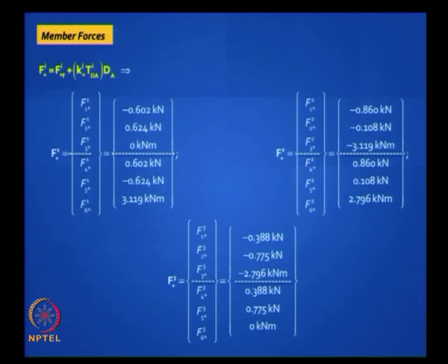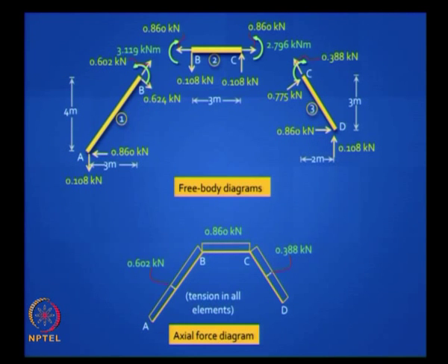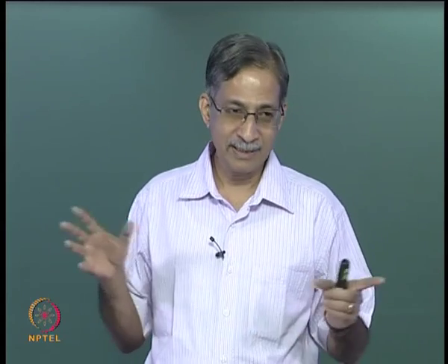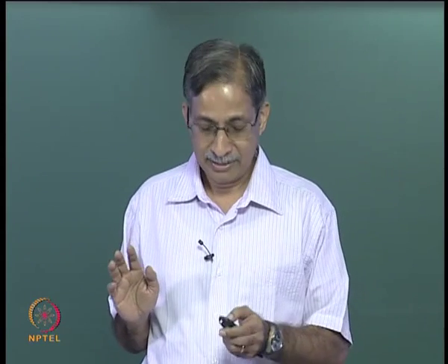You see that value which we got, 0.9 for the second element, the exact answer is 0.86, which is close to 0.9. And these are your final diagrams. You got your axial force diagram, shear force diagram, and bending moment diagram. The axial force diagram is more critical among these, and you will find that they are very small. Okay, so this simple problem teaches us many things and shows us the power of matrix analysis. So now with this we finished the conventional stiffness method.